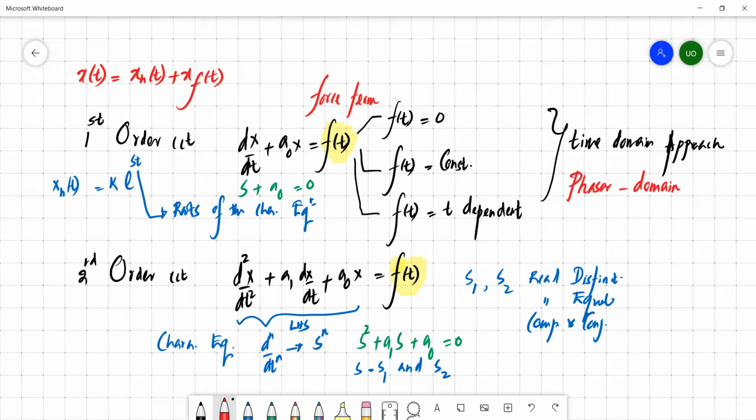You convert the electronic components in the circuit to the complex domain by replacing all inductors with j omega L and capacitors with 1 over j omega C, and all the sources can be replaced with a magnitude and a phasor. Then every parameter in the time domain is simply mapped to the complex domain.